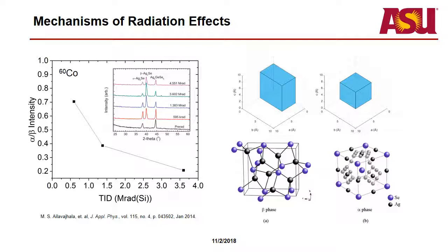So for the beta phase, since it's a semiconductor, it doesn't really allow ion migration all that efficiently. You can still get ions through, especially through the voids, because it is a glass, so it is an amorphous structure. There are gaps big enough to get the silver ions through and to hop through with different defects throughout the material, but it's not going to be as efficient or as fast as when the material has silver selenide in it. Alpha phase of silver selenide.